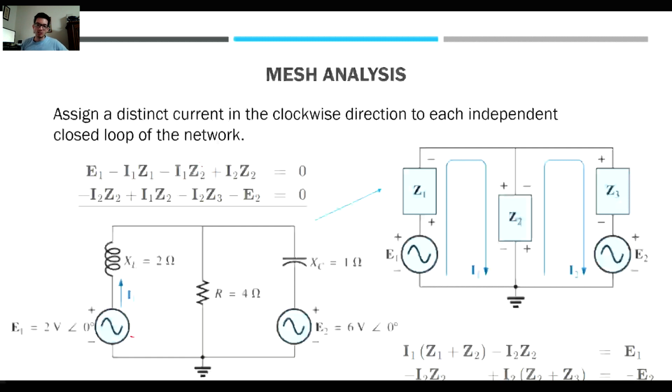But you need to assign the initial convention as you please. As a rule of thumb, you would put the first loop with negative close to the ground. So you're going to have negative and then positive. And here you can do whichever you want because it's a load. Since it's a combination of circuits, obviously there's going to be one going backwards given the magnitude of the current.